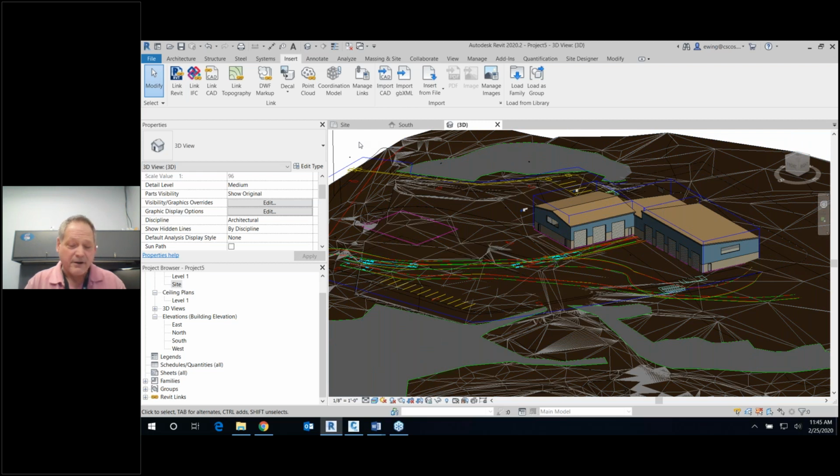And the BIM 360 part, I just learned that the hard way on a project on shared coordinates, and coordinates moved, and guess what? All of our models had to come off of BIM 360. And it doesn't happen when you're starting the project. If that occurs, it happens the day the project's going out, right? Most of my lessons I've learned have been the hard way. I hope I answered your question.